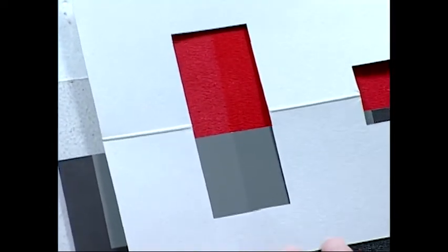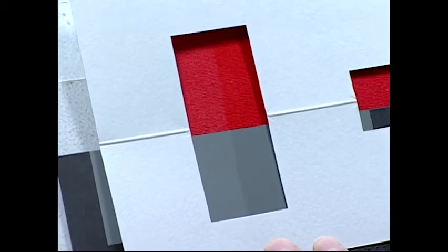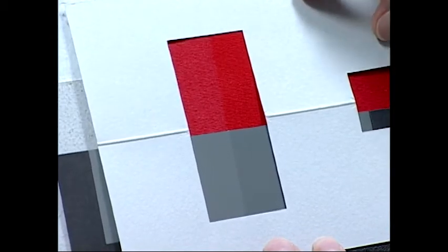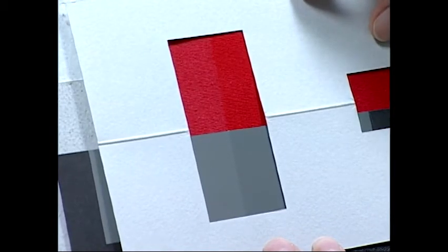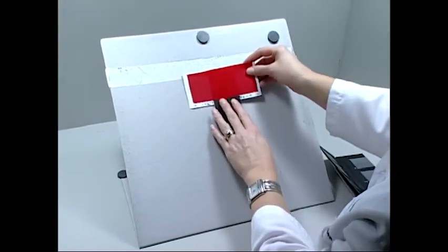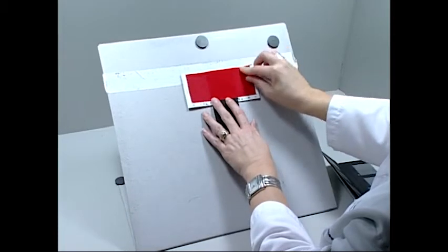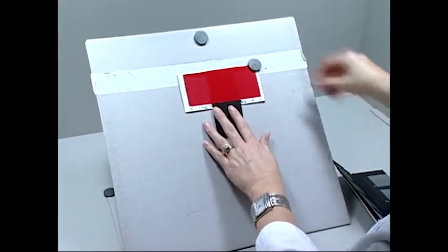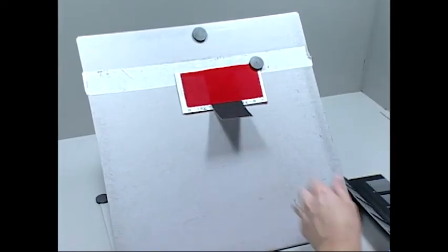This procedure is used for tests such as light fastness, laundering, accelerated laundering, perspiration, and finishing. Here, the rating is done horizontally for ease of demonstration. The actual rating would be done vertically. To execute the rating, a piece of the original non-tested textile and its corresponding exposed test specimen are placed side by side in the same plane and oriented in the same direction. Special care should be used to have straight edges for each specimen, which are placed side by side.